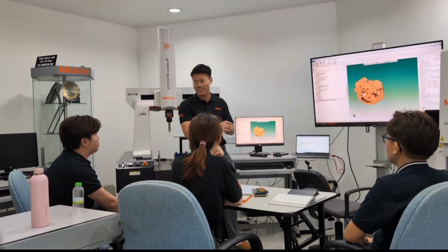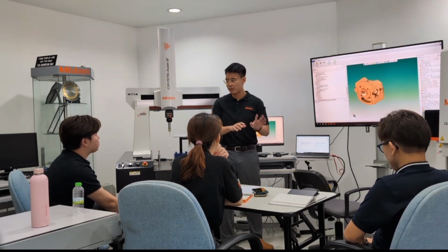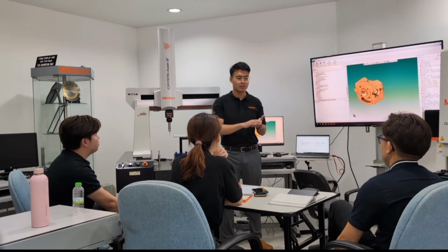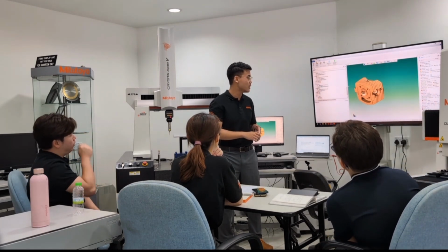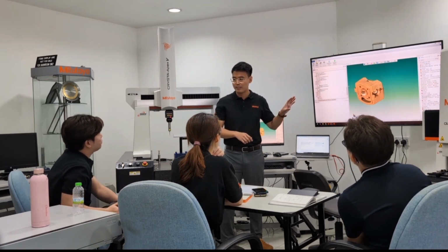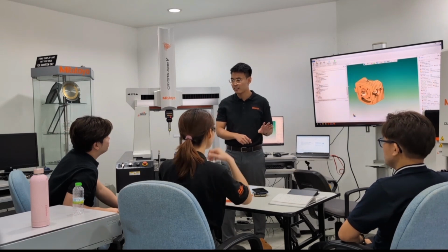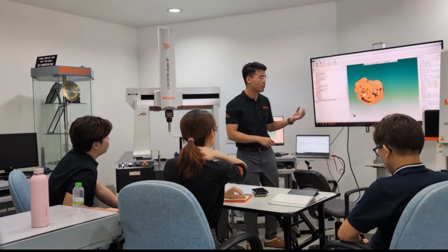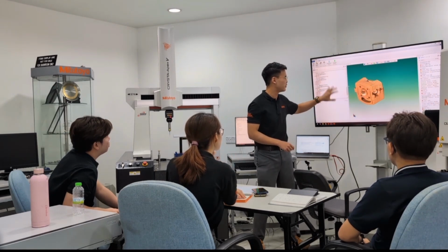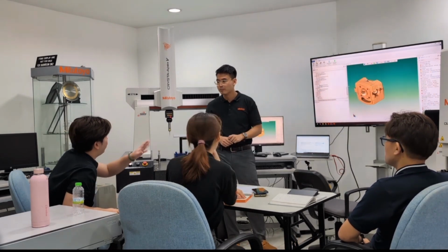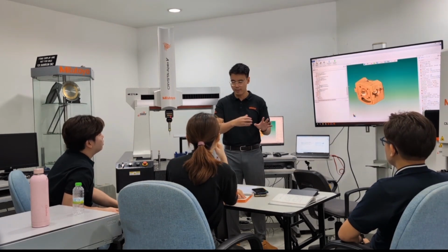Speaking about PMI data, there are actually two kinds of PMI data. One kind is called graphical PMI data. Graphical means that it only shows graphically, but it doesn't bring any data inside. So even though you import it and it shows here, it doesn't carry any information that will relate automatically. It's only graphical, it doesn't carry the important data.